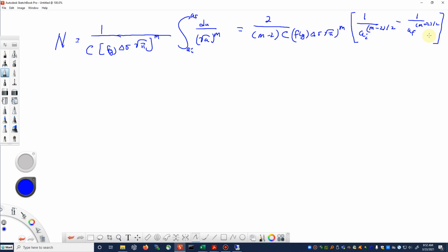All right, so let's take a look at this for a little bit. We're going to run into trouble if we end up with our material constant equal to 2. All right, so you will see m often in the range of 4. If you end up with m equal to about 2, see if you can find another pair of fitting constants that work for your data.